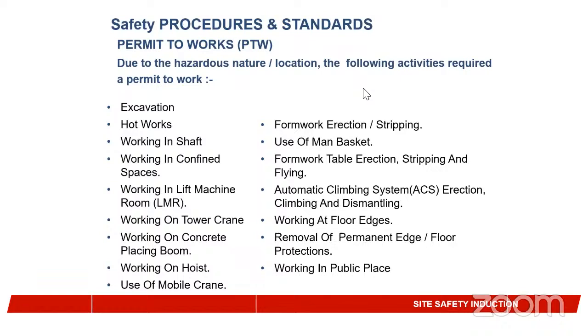And it's not only assisting the safety professional alone, it also assists the engineers, it also assists the supervisors, because it's like a system that addresses so many things in the workplace. Before the start of work, there should be a permit to work that permits a particular worker to do a particular job. His name is written, he signs that he is doing this job in this particular location. Each location should have its own permit to work. And the risk, the hazard that has to do with the job have been addressed and also communicated to the worker.